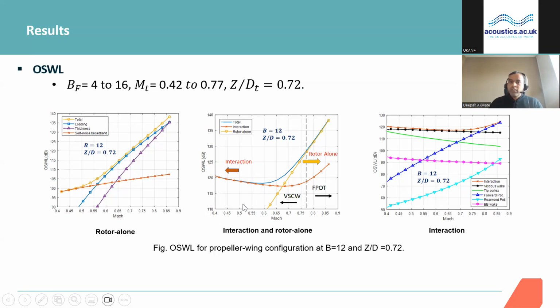So to generate similar thrust, one needs to generate a higher lift, or a higher lift coefficient. For that, the propeller runs at higher pitch, which increases the drag coefficient, which increases the drag on the propeller. And we know that the tonal viscous source strength is proportional to the drag coefficient of the propeller, which increases the overall wake interaction noise source. So that's why the wake interaction noise source increases as you reduce the tip speed.